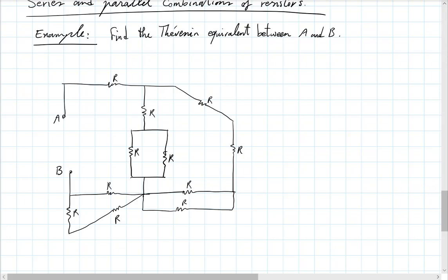Well, let's see. If I wanted to follow the recipe that we came up with before, I'd say, well, let's start with step 1, find the open circuit voltage, right? Which means between points A and B, I just connect a voltmeter, which means ideally, essentially nothing imposed on the circuit, just a pair of eyes that will tell me what that voltage is between A and B without doing anything else. In other words, this is left open. I just measure or calculate the voltage between A and B. Now, what will that be? 0.